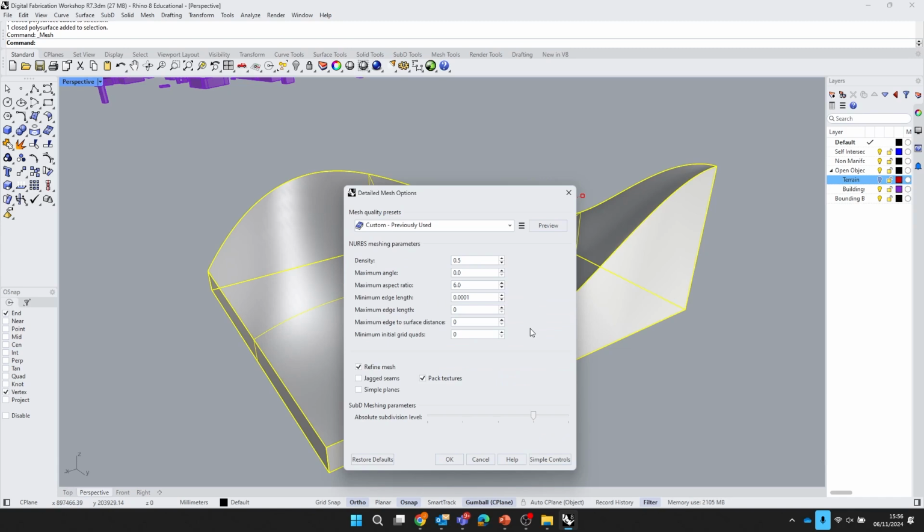So how long do I want edges of polygons to be? Is there a maximum, a minimum? For instance, if this is making a really dense model, but if you're printing to low resolution, like 0.1, set your tolerances as 0.1. You're never going to end up with extra resolution that you don't need. It will make your files faster and more optimal.